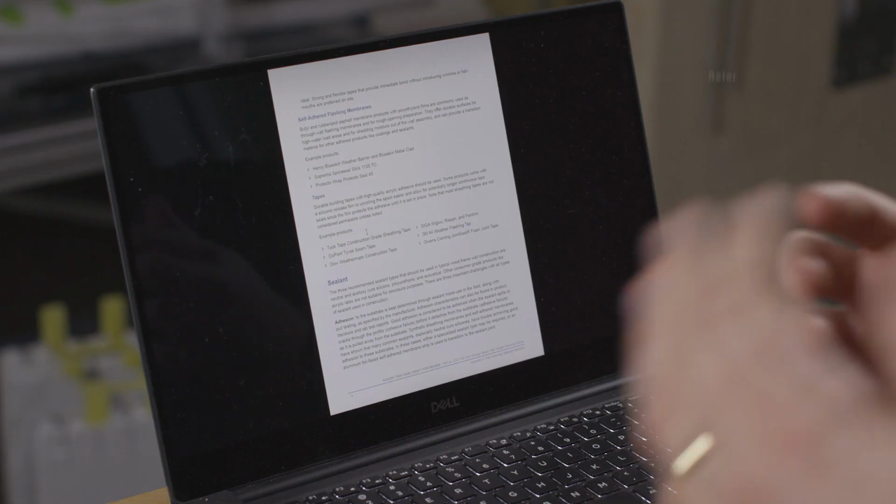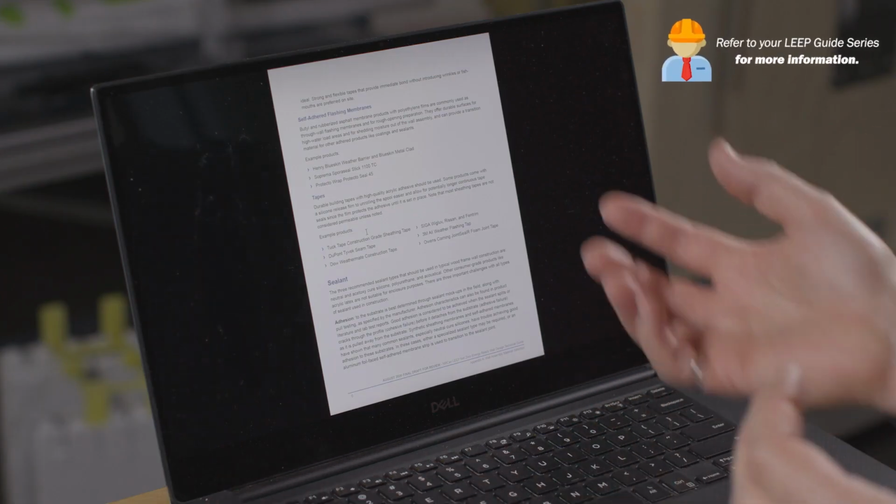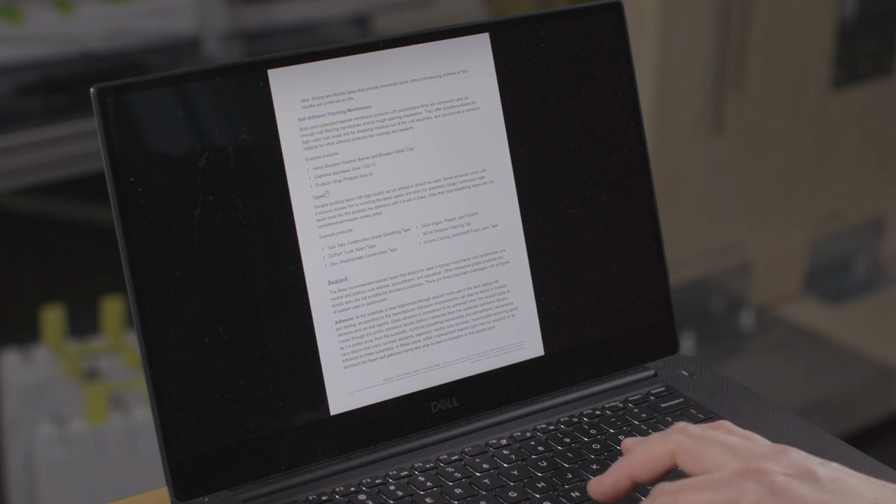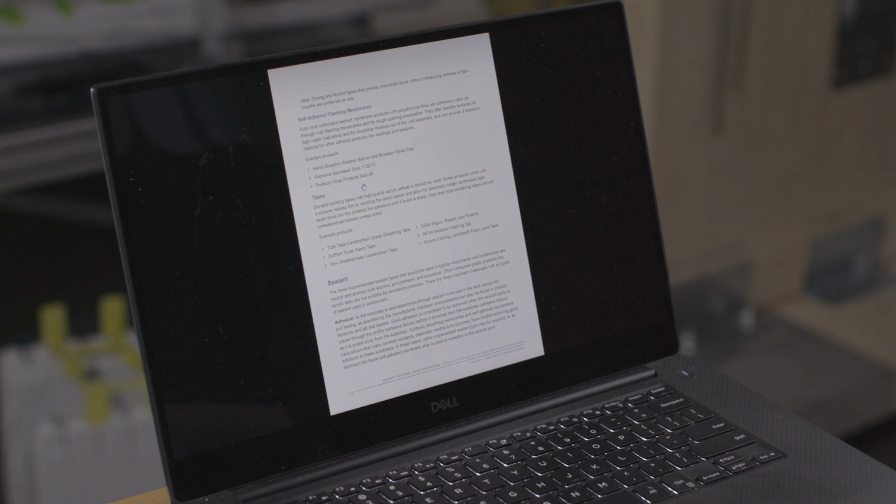And so what you're looking at there is adhesion, the workability, how tough that material is, and how it's going to stand up to the details. The big thing with a lot of these self-adhered membranes and flashing membranes is, do they need primers or do they not? And so following the manufacturer's recommendations for that is critical. Example products: Blue Skin, Supremas, Seal Stick, Protector Wraps, Protective Seal, and there's dozens of other peel and stick products that can be used in this application.